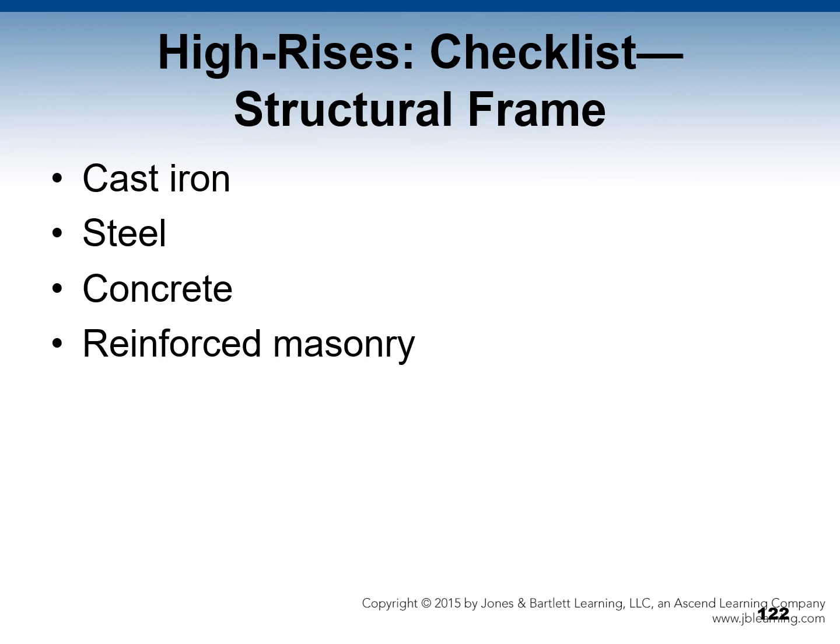If there's steel, what type of fireproofing is used? Are columns unprotected in the plenum space? If there's predominance of concrete, are there visible rods and cracks? Has there been any fire experience in this building that might have caused structural damage? Is corridor fire resistance achieved by gypsum on studs, making breaching easy? If there's a lot of reinforced masonry, are there corridor walls that are reinforced?